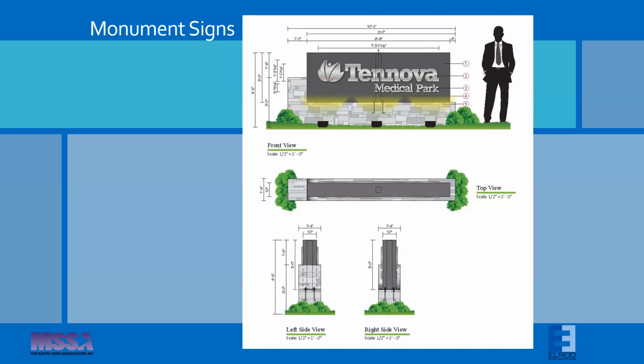Instead, we came up with an approach where a short stub was installed from the top of the foundation to the top of the CMU block base. And then the cabinet pipe itself was connected to the match plate. Problem solved. Again, I like to use this example because working with an engineer who actually understands what you're trying to accomplish, they won't just analyze the drawing and give it back to you. They'll think in terms of what does code allow and make sure that what you're proposing to do actually will get approved in the event that an inspector shows up and starts to question things.